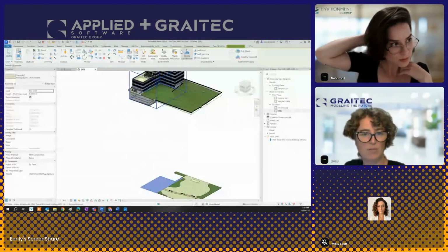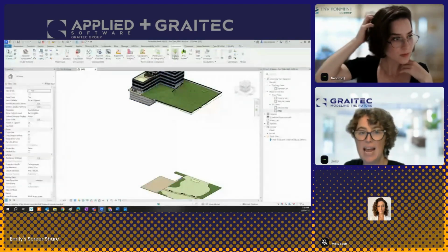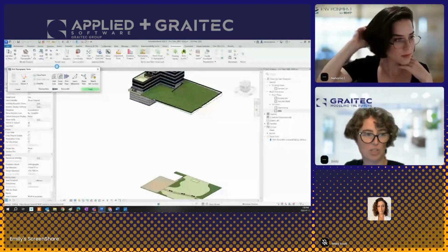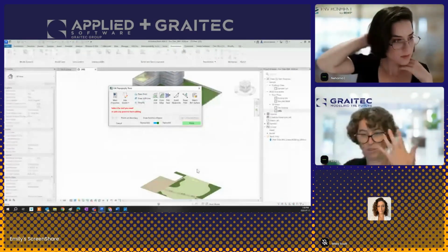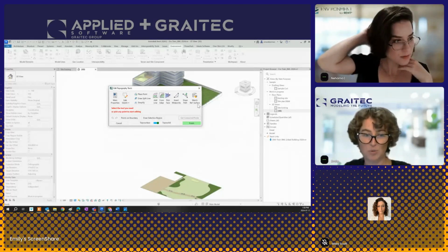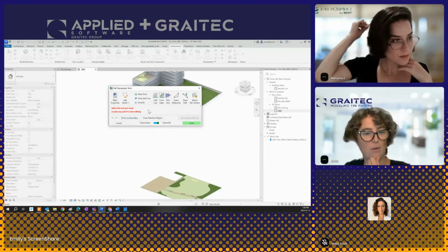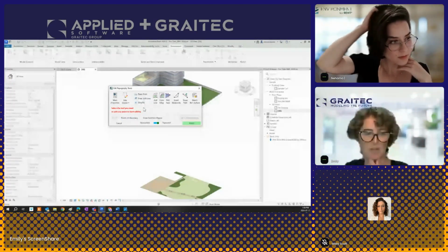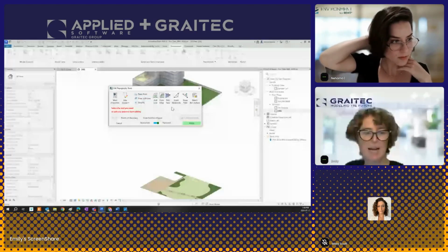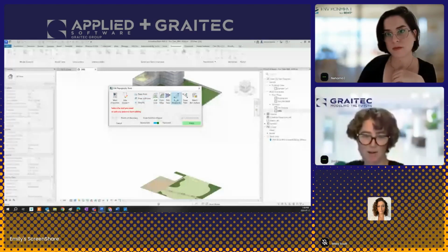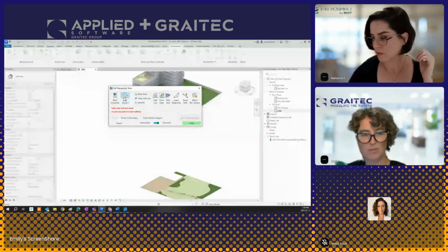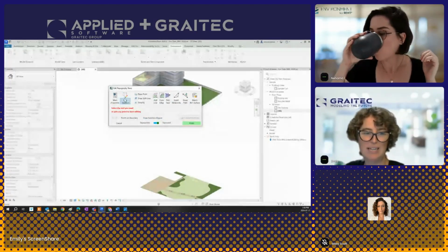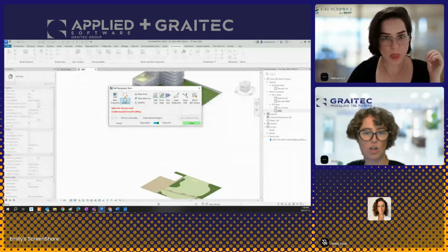These tools have now been carried forward. As you can see here, this is a topo solid, and the topo solid tools are in the topography tools now in Environment for Revit. So you do not have to switch. You're always in the Environment tools in this one window when you're working. So everything is here in place. Point, draw a split line, and also adding and modifying all of your tools, including the reference surface. This Edit Sketch is for your reference surfaces and any edits you need to make to the shape of your topo solid.